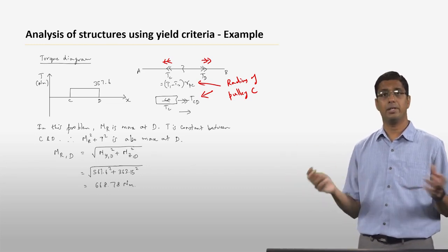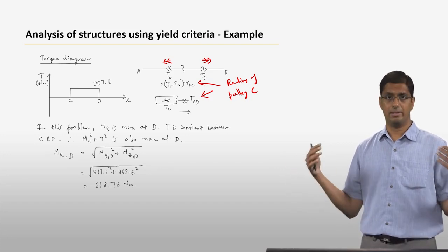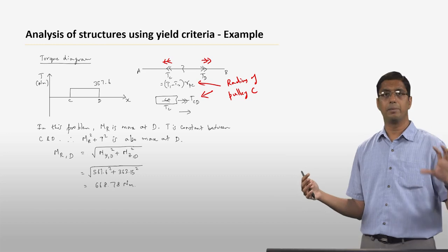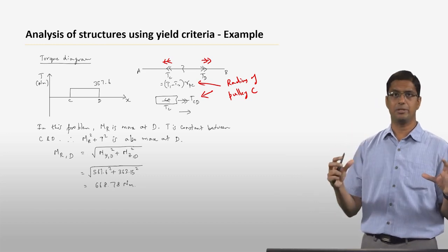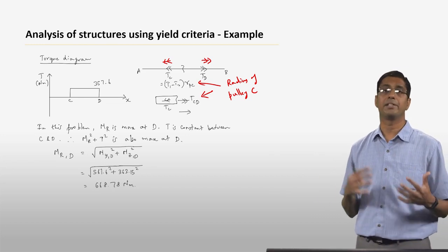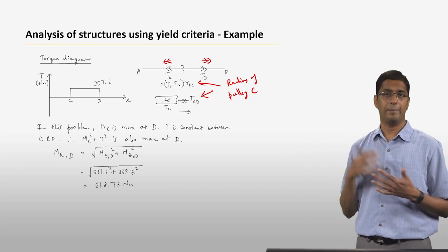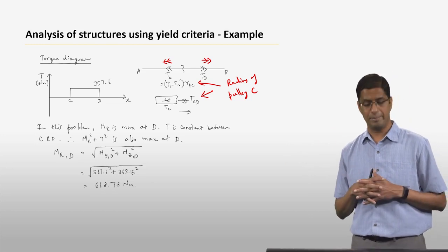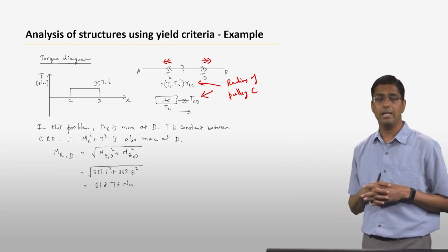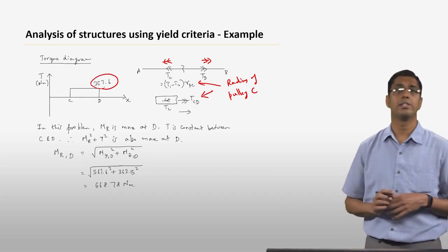And these two torques have to balance out each other because there are no external torque reactions. So the torque on pulley C has to be balanced out by the torque on pulley D. So essentially you can use either one, either T1 minus T2 times RPC or T3 minus T4 times RPD. Both will essentially give you the same answer. But anyway, the magnitude of that torque turns out to be 357.6 Newton meters.